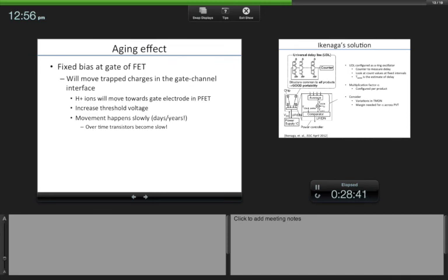For example, in the case of a PMOS, again, a very important region for any transistor is the interface between the oxide and the channel. You have a single crystalline silicon, but at the surface, the bonds are dangling, right? So that is where you always have issues related to mobility, performance issues, etc. So those bonds have to be passivated, and you might have some ions like hydrogen ions and so on. And then if you have a prolonged, for example, in the case of a PMOS, when you turn on the PMOS transistor, the gate is at ground, so it's at the negative voltage compared to the source, right? That is why it's called negative bias.